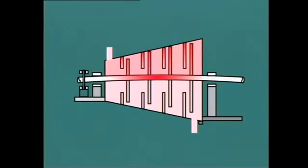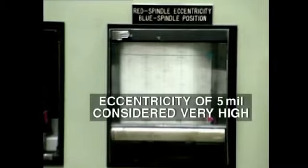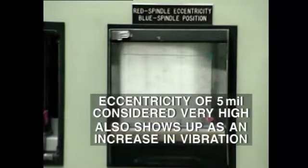force of rotation. Eccentricity is dangerous because it results in a reduction in radial clearance between the rotating and stationary parts. The degree of eccentricity is measured and recorded at the operator's terminal or control board. In most machines, an eccentricity of 5 mil is considered very high. High eccentricity also shows up as an increase in vibration at the bearings.